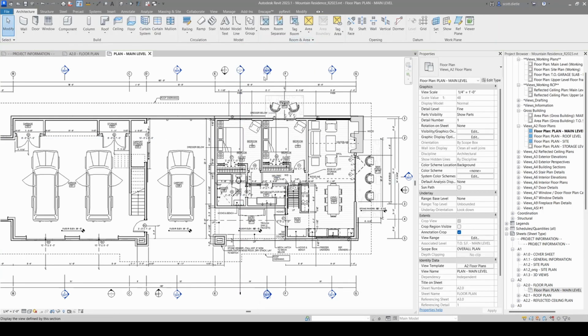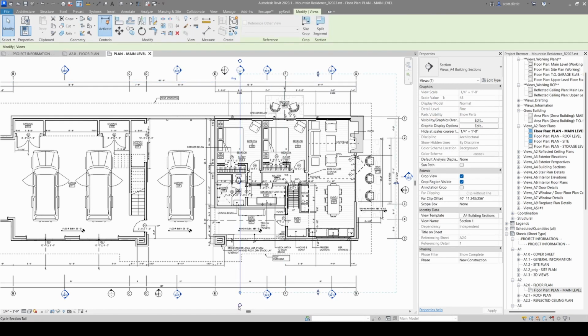Okay, first thing we want to do is make sure our section looks like other sections in the model. So the head appears to be correct, but the tail, we want to swap that out for the rounded tail. And then we'll use this dot, drag it up. And normally you would think if you get close to these, it would snap into place. Revit with sections has a small glitch where you actually have to pull your section way out past what you're trying to snap.